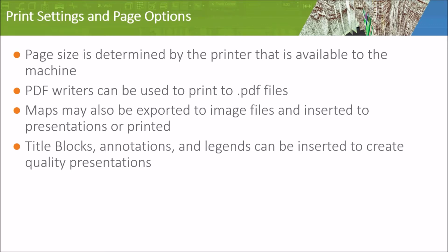Your maps can also be exported out to image files, whether it be JPEG, PNG, TIFF image, whatever you wanted to export it out as. That then can be inserted directly into a PowerPoint presentation, or you can print the image directly as opposed to going through GeoAtlas if you want to do it that way. With those maps, whenever you export them, the key aspect is going to be what your DPI is, your pixel size. The larger it is, the larger the file will be. So just be aware that you control some of that. But again, the larger you go, you may run into some memory problems depending on the image loader. And then title blocks, annotations, and map legends can be inserted to create your quality presentation there in the page view. And we'll look at how you can customize some of that as you go through and build out that map.